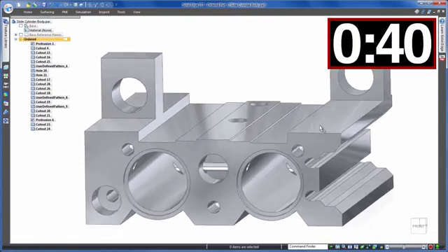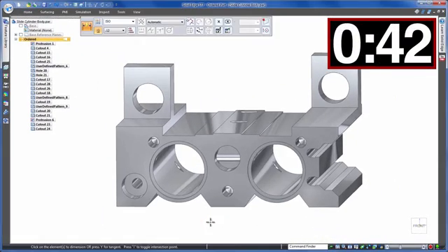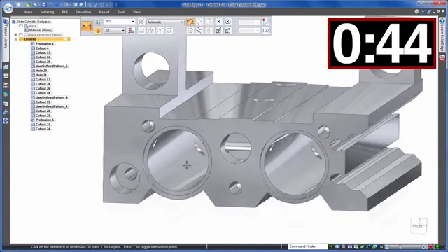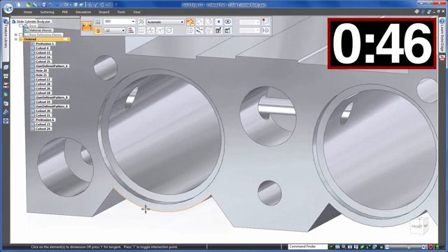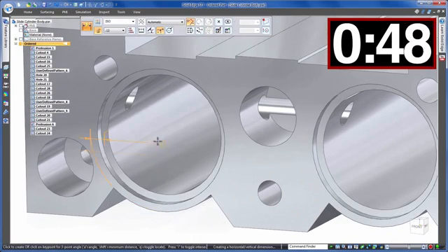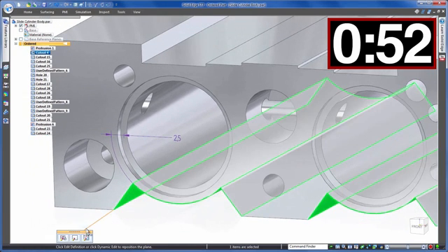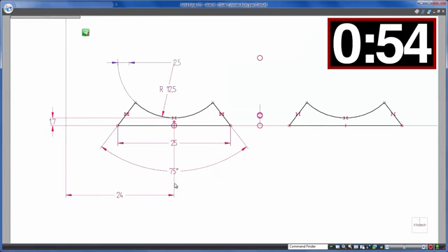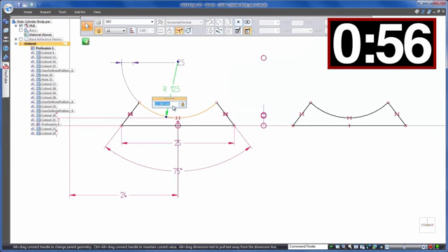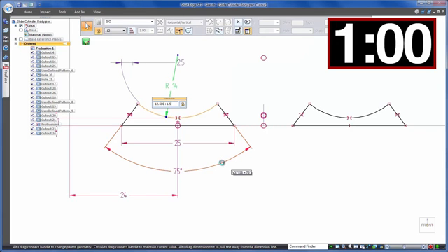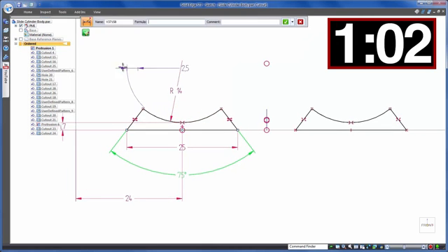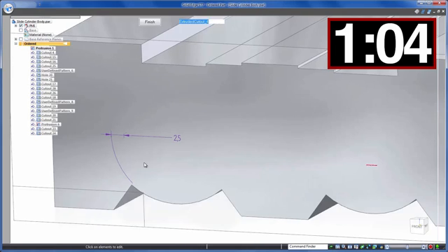Back to history base for the next change, and before we make any edits, we need to find out how much material we currently have between the cylinder and the cutout. Measuring it finds it to be 2.5mm. We need to make this a total of 4, so we'll add 1.5mm to the radius of the cut. Again, we'll go in and edit the sketch of the feature and use Solid Edge's ability to enter equations in the dimension box to simply plus 1.5mm. Rebuild the model and...